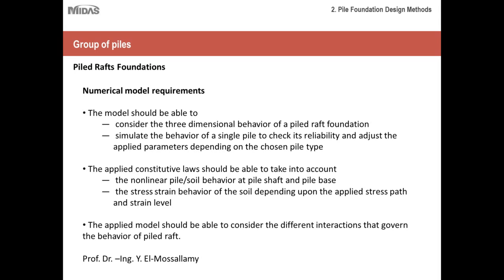It should be able to simulate the behavior of a single pile to check its reliability and adjust the applied parameters depending upon the chosen pile type. So this means before blowing up your model into full 3 dimensions with all the pile members, we should first make a 3-dimensional model of a single pile, verify its results with the field data, and then apply those parameters to a 3D analysis model.